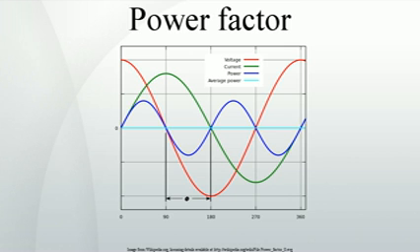If a purely resistive load is connected to a power supply, current and voltage will change polarity in step, the power factor will be unity, 1, and the electrical energy flows in a single direction across the network in each cycle. Inductive loads such as transformers and motors, any type of wound coil, consume reactive power with current waveform lagging the voltage.